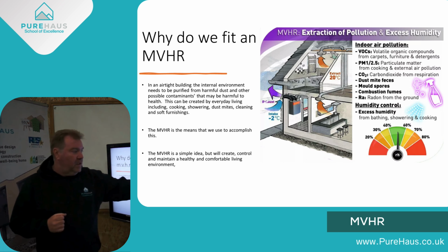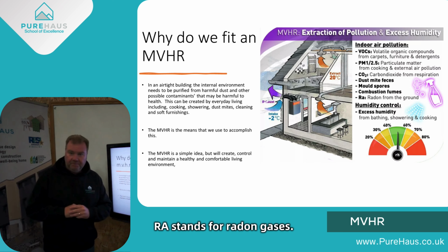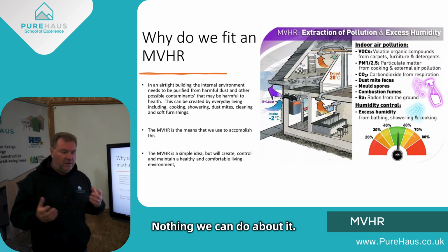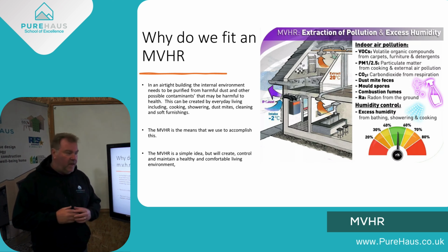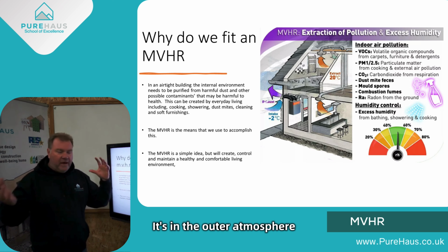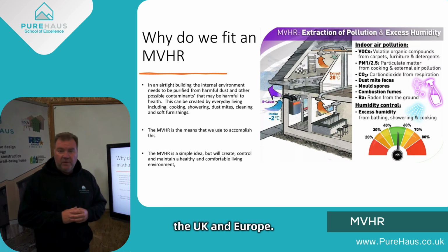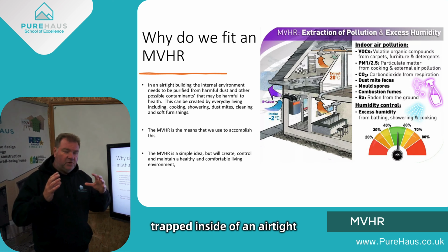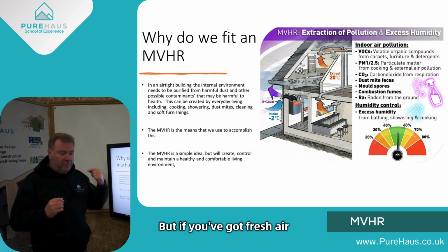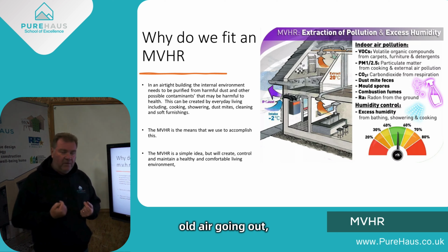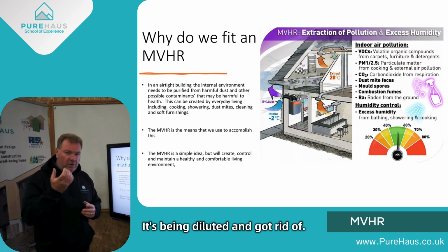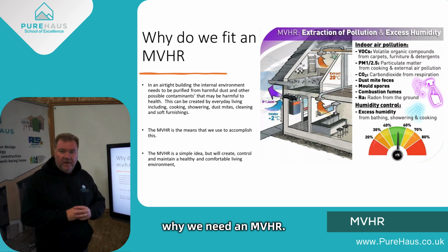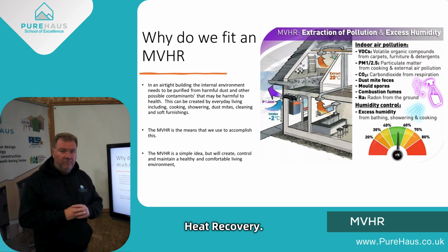Radon. Radon gas is a naturally occurring gas in the ground. Nothing we can do about it. It's there. It's always going to be there. It's in the outer atmosphere in many places around the UK and Europe. And it can get trapped inside an airtight build. But if you've got fresh air coming in and you've got the old air going out, it's being taken care of. It's being diluted and got rid of. So these are the reasons why we need an MVHR, mechanical ventilation and heat recovery.